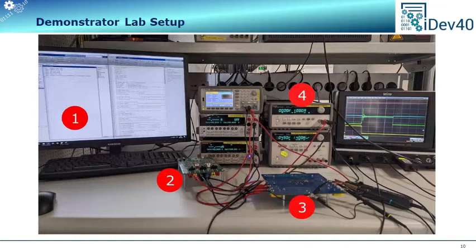It represents a resistors board controlled with SPI to set a series of series or parallel resistors in order to obtain a value as close as possible to the load current required for the measurement. The second board, number 3, is the DUT, the design under test board having the chip to be tested embedded into it. Besides it, there can also be found some additional components such as the input or output capacitor, and it also helps us connect the required measuring instruments needed for the test.